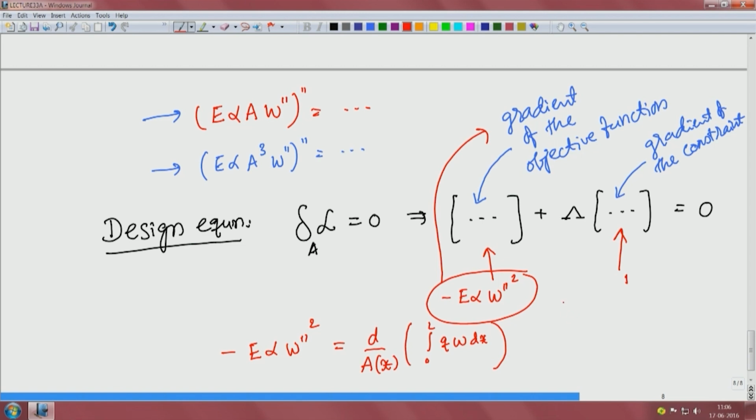I have a beam, okay, let us draw a beam profile, let us say this is optimum, somebody has told you it is an optimum. Now, or even otherwise some profile is given, let us say this is our x, at some value of x, if I change the cross section a little bit, okay, let me use some color, some material I want to add, then obviously under the loading Q, if I compute W by solving the equilibrium equation, I will have a different mean compliance, right, compared to the one without this additional blue, right.